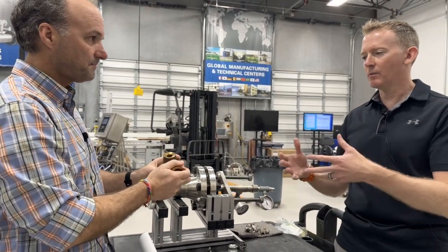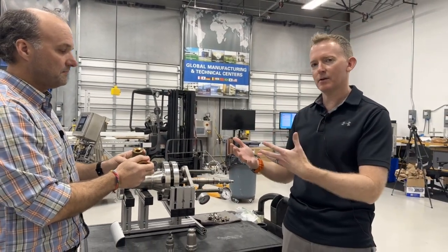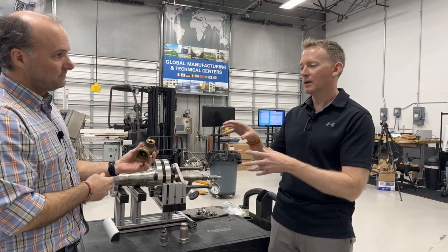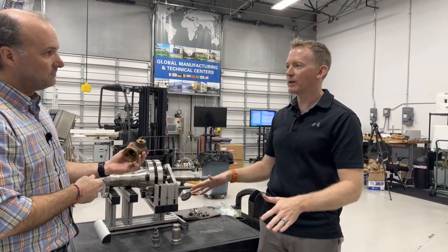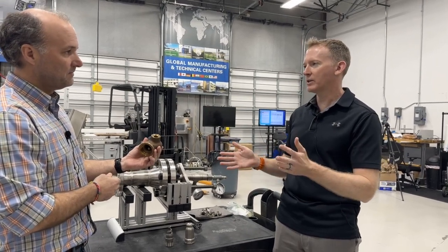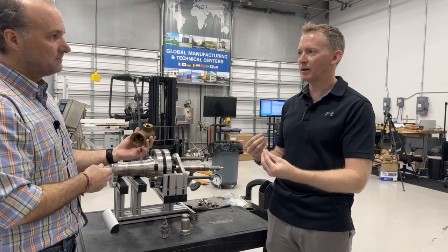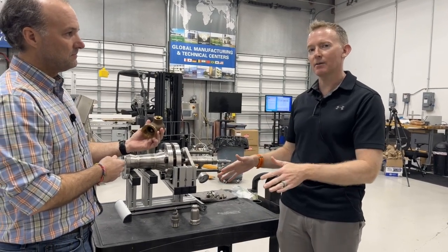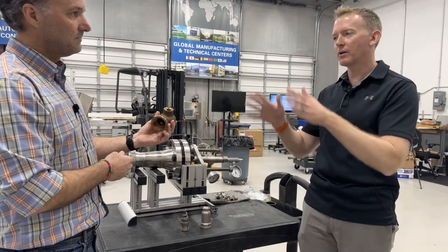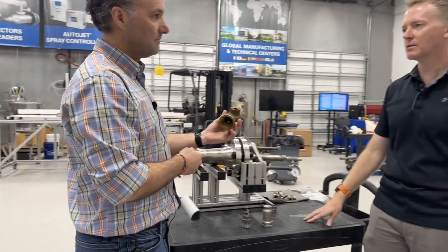Absolutely. One of the reasons why, just from a coker process guy's perspective, I like this nozzle is because it creates kind of a curtain of liquid that the vapor has to pass through. And it has a better washing effect. We're not going for mass transfer here. We're going for washing, right? So forcing the vapor through a curtain of liquid, to me, seems to make better sense.